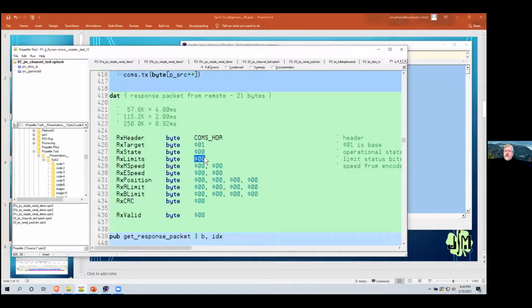There are these metal clamps that go onto the rope that John has these really sensitive inductive sensors that will provide a signal that will know if we've gone past the soft limit, so we don't actually crash into something. So there's actually 4 limits. We have 2 soft limits, 2 hard limits.